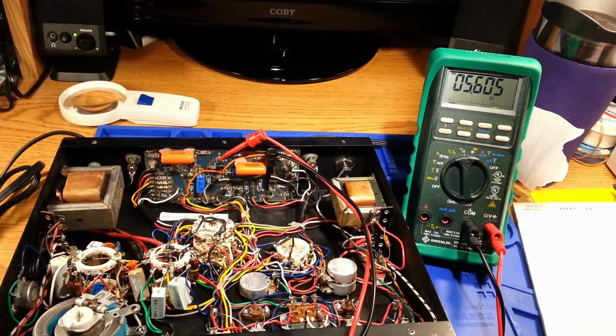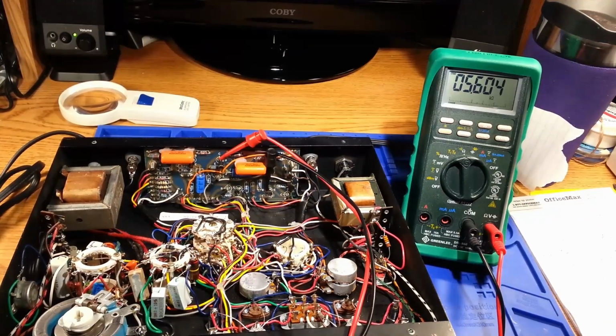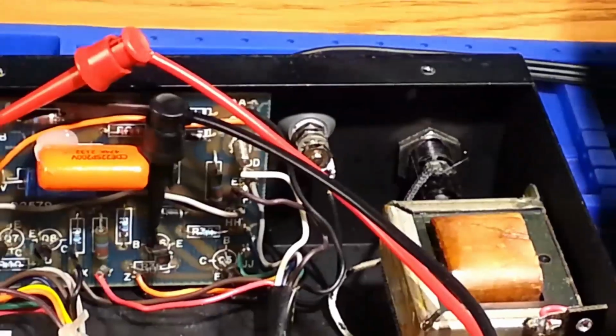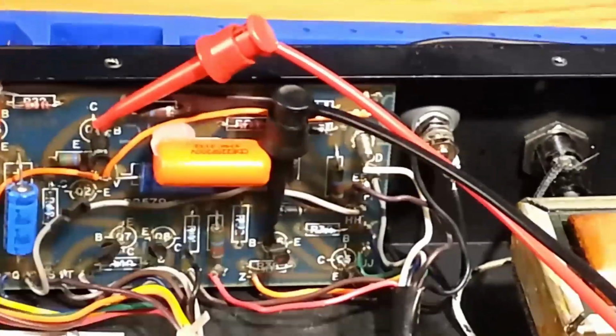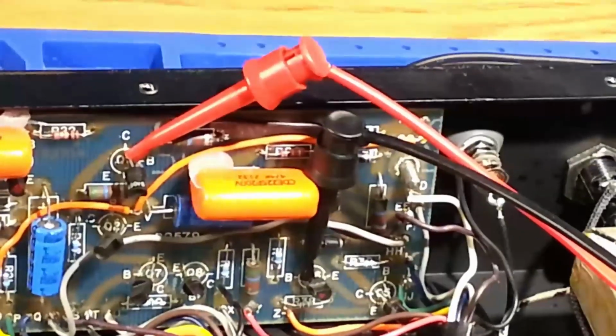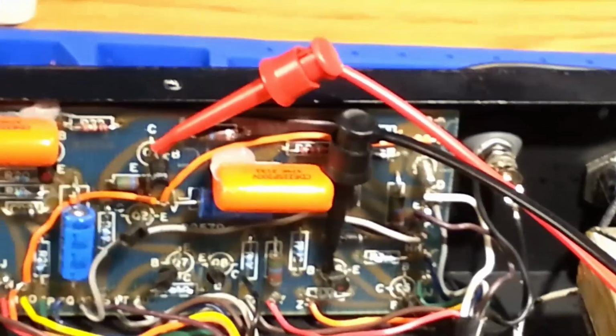Q1 and Q2 are correct, and looking back on the schematic that I have, since Q1 and Q2 are correct, I am trying to look and see where they're tracing out to. In this case, the collector of Q1 should go through a 5.6 kilo ohm resistor and go directly to the base of Q3. And if you look, that's what I have my meter connected to. I have the collector, I can't see the number there real well, but